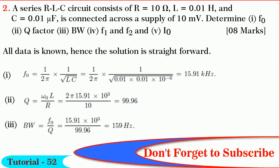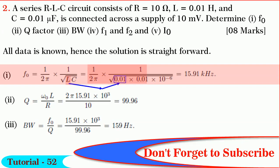We know that f naught is equal to 1 divided by 2 pi into 1 divided by root LC. By substituting L is equal to 0.01 Henry and C is equal to 0.01 microfarads and solving, we get f naught is equal to 15.91 kilohertz.